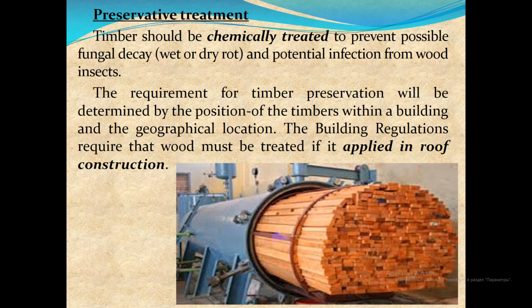Timber can be specified to be chemically treated to prevent possible fungal decay, wet or dry rot, and potential infection from wood insects. The requirement for timber preservation will be determined by the position of the timbers within a building and the geographical location. The building regulations require that wood must be treated if it is applied in roof construction.